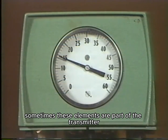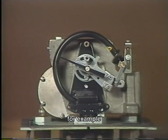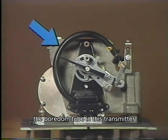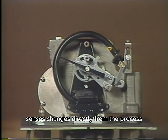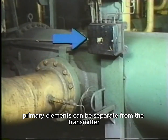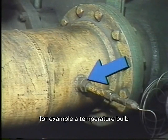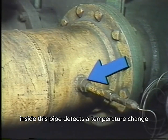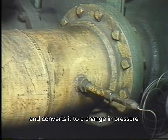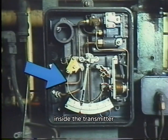Sometimes these elements are part of the transmitter. For example, a bourdon tube is often part of a transmitter. The bourdon tube in this transmitter senses changes directly from the process. However, primary elements can be separate from the transmitter. For example, a temperature bulb inside this pipe detects a temperature change and converts it to a change in pressure, which in turn is detected by another sensing element inside the transmitter.